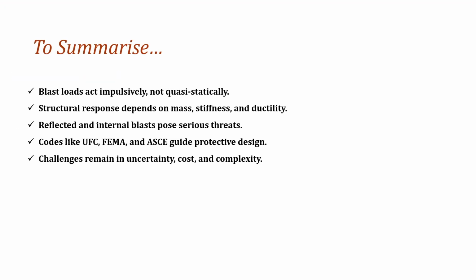We are summarizing whatever we have learned till now in the introduction part: blast loads act impulsively, they are not quasi-static. The effect of the blast loading is characterized by very high pressure occurring in a very short time. They pose very high risk of catastrophic failures. The structural response depends upon its mass, stiffness and ductility.